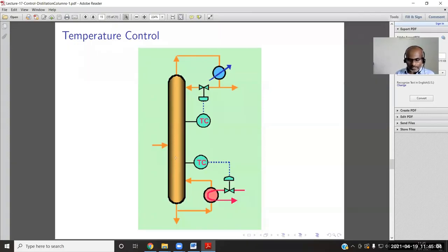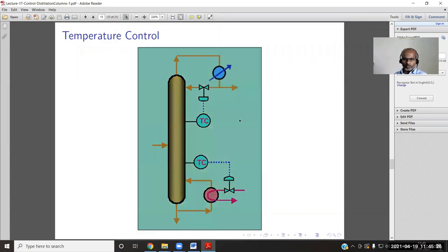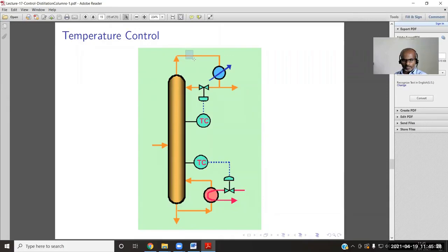in the distillation column. Of course, for distillation, whatever you studied for the heat exchanger, you can write the same thing here. So wherever there is a temperature control, how do you implement this feedback? So measure the product outlet temperature and take control on the flow rate to the heat condenser. That is a feedback control. And feed forward could be measuring the flow of this distillate and accordingly controlling the flow. So there is a feed forward control.